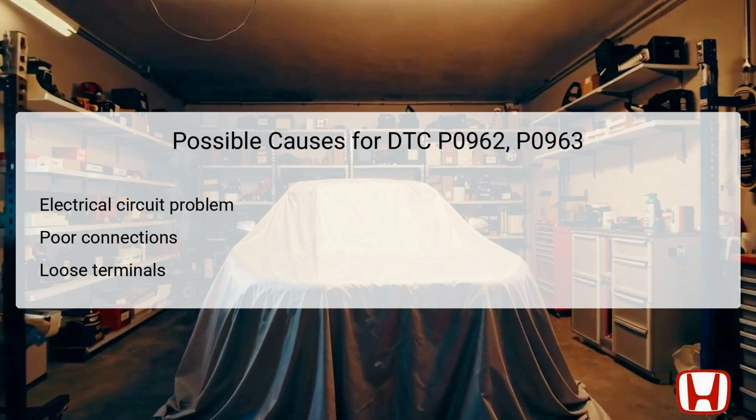It's vital to differentiate that the root cause lies strictly within the electrical wiring, connectors, or components related to the valve circuitry, as no mechanical faults in the transmission are responsible for these codes. A detailed examination is crucial to either isolate these faults or confirm connectivity integrity before proceeding with further specialized tests.